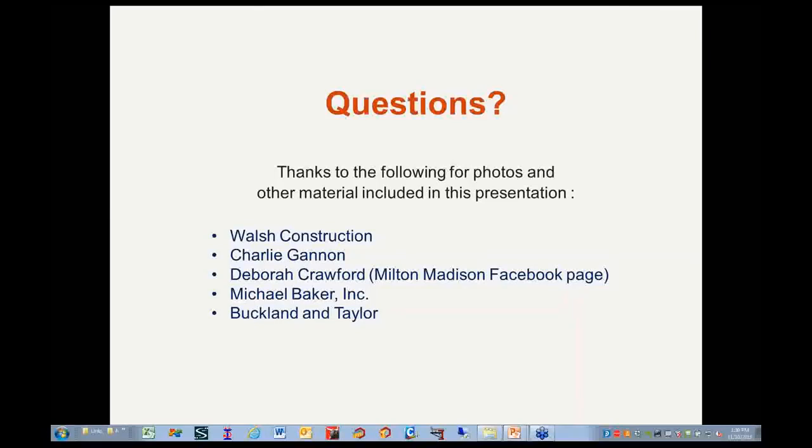Okay, and so far, this looks like the final question. Was conventional analysis of the pier foundations performed in order to validate the results of the finite element modeling? Yeah, going back to the first question, yes, that was actually done prior to our involvement by Michael Baker. The type of analysis we did was mandated by the scope of the project, and they did validation of that analysis type with L-Pile and conventional software before our involvement.